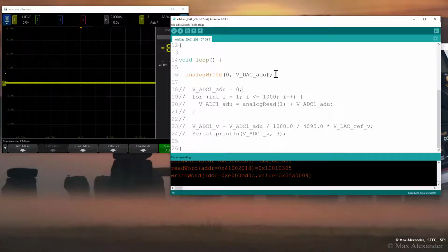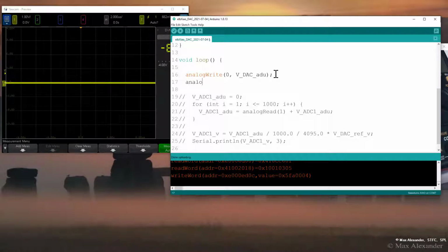And this is going to turn the DAC pin 0 on. I'm going to turn it off. So I'm going to do an analog write. It's pin 0, and I want 0 volts coming out. This is just going to toggle it off and on, off and on, off and on. Okay, let's run it, and then we're going to look at the output voltage, which should be a square wave with a 2 volt peak to peak, 0 to 2 volts, and we'll look at the features of